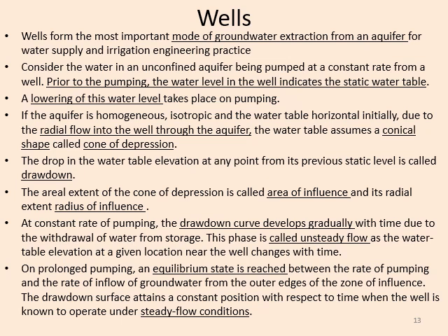So at a constant rate of pumping, when we are pumping for a much longer time, a drawdown curve will develop gradually. A drawdown will develop, and if we join the points at different distances, it will give a drawdown curve with time due to the withdrawal of water.